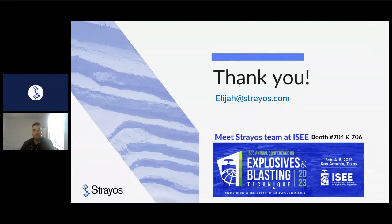But I would say adjusting your product selection if available, and maybe putting a deck in to break up that top layer of cap rock, whether it's a small diameter stick product or larger diameter, even just a larger booster or primer to break that up, I have found to be effective in that issue.